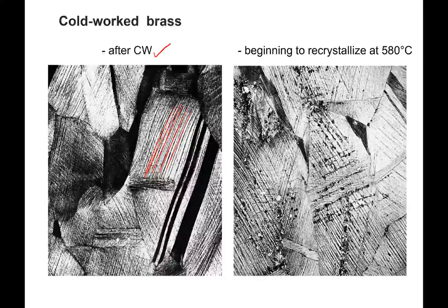Well, all of these dislocations mean that you've just created a sample with a very high energy. It has a lot of plastic strain, a lot of deformation in it. And so if we were to heat the sample up to a high enough temperature, what we can do to get rid of all of these dislocations is actually take a piece of that original grain, right? And we basically nucleate a new grain. So the atoms in that area by diffusion get together, they eliminate that dislocation in that area, and we get a brand new crystal forming. Nucleate a new crystal here, new grain.